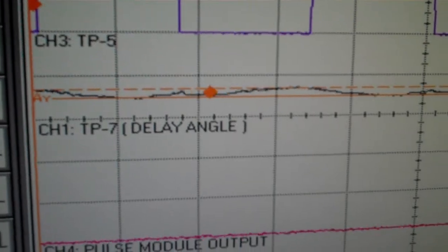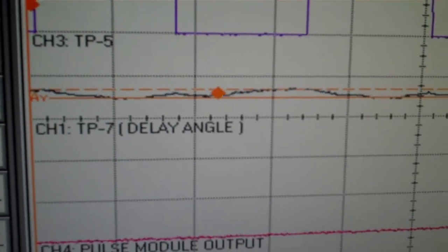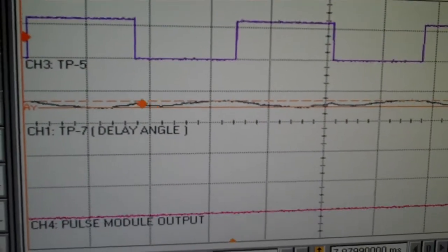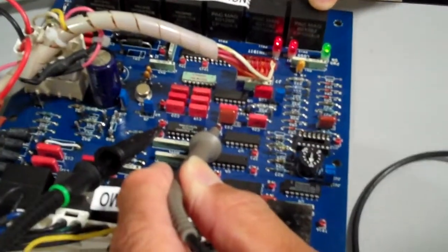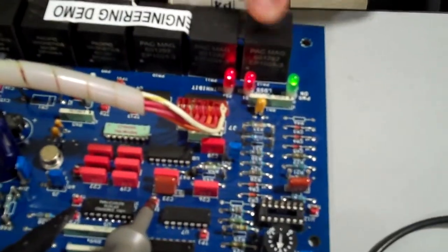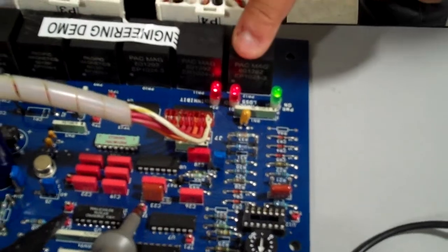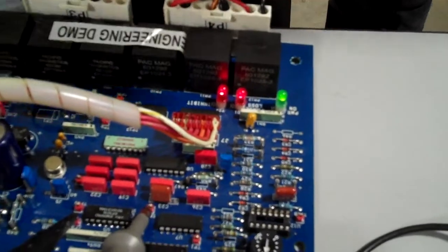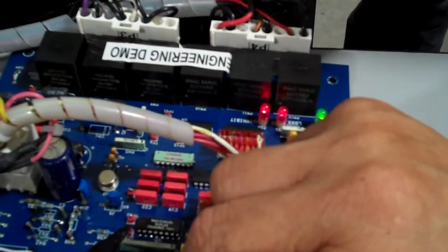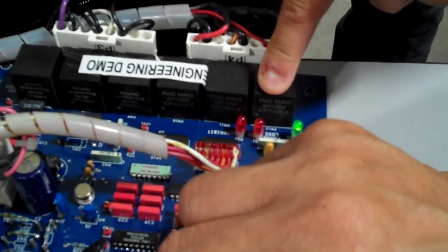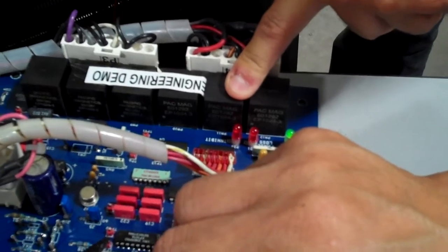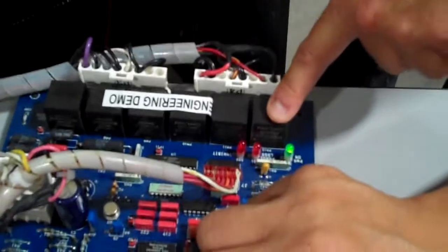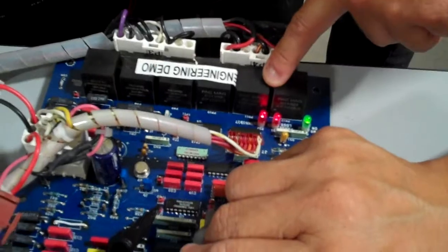Just the fact that it got distorted is enough to be outside that threshold. And then we have here on our board a red LED, and this is basically the condition that you have. If you have a red LED, the board will never enable. Go ahead and clear the enable, and we looked at the LEDs. If we clear the phase loss, the board was already commanded to enable, so the board will enable. But if we induce a phase loss, the board will immediately inhibit.